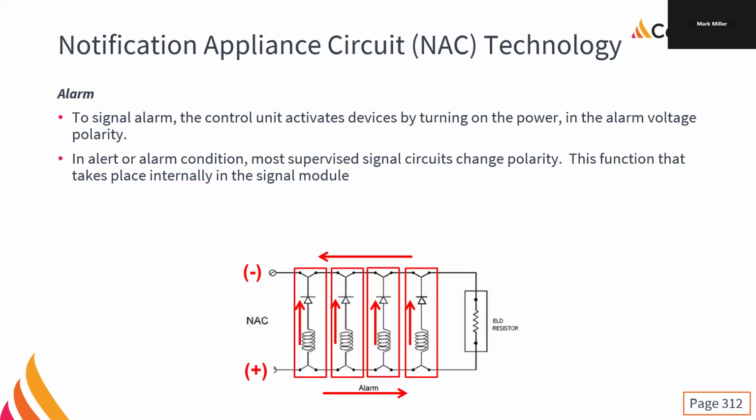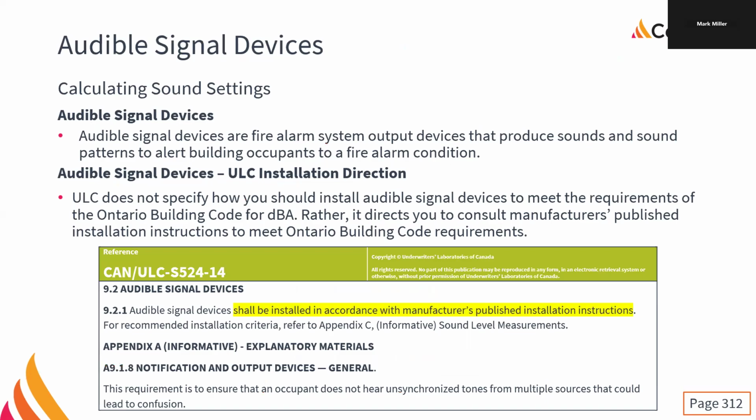We can take advantage of the design of the bells and horns and strobes to troubleshoot them very, very quickly. Fixing it is another thing, especially if you're dealing with a pile of people who are doing the connections of the devices who are, I wouldn't say color blind, but color stupid. You could get some messed up polarities here and there, and at that point, you see which direction has the fewest problems, and you make that your officially correct, since the wire colors is just a recommendation, anyways.